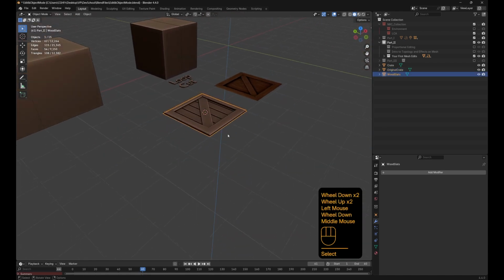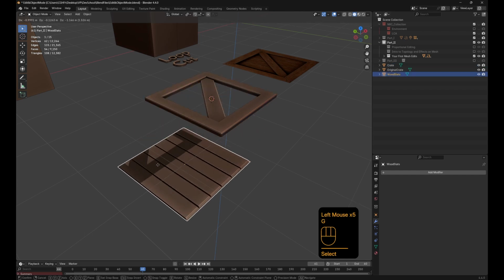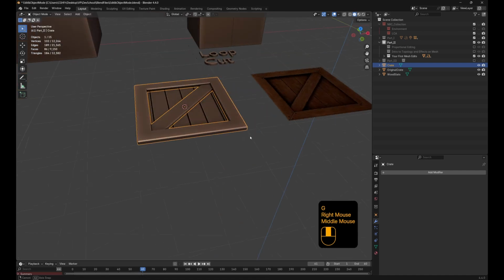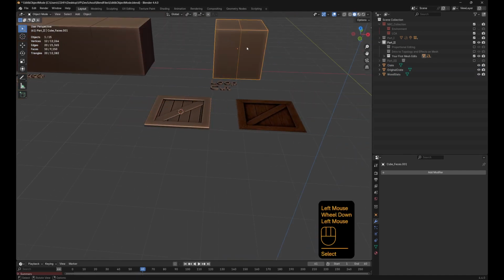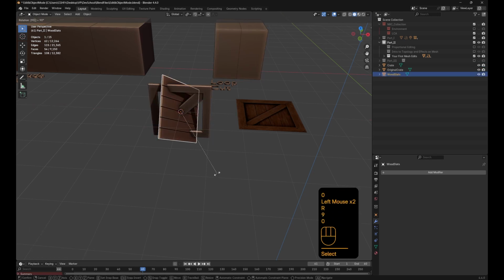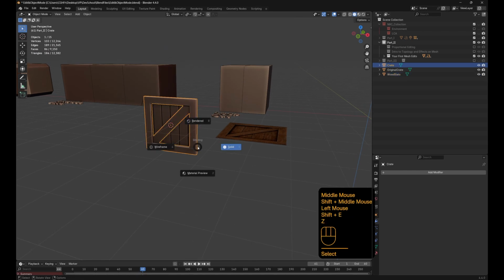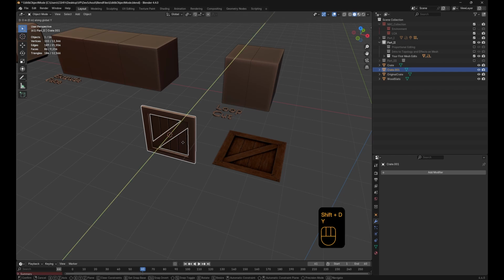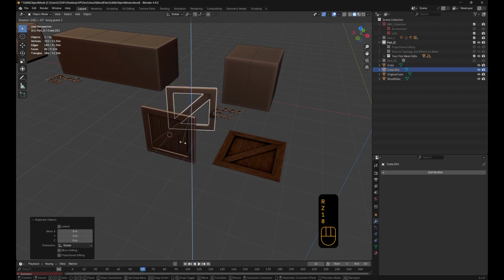The last thing I'll do here today with you is to join these 2 bits of mesh together. So I've got the wooden planks and I've got the outside frame of the box as well. Now, it's important, if we were building this on a cube, if you imagine this was 3D, so if I rotate that 90 degrees on the x-axis, let's actually build it for you. I just duplicate Shift and D on the Y by 2, okay, and then rotate that by 180 degrees on the Z axis.